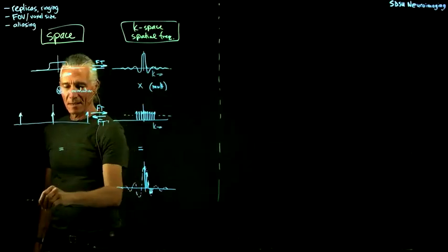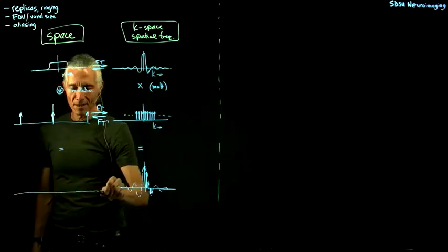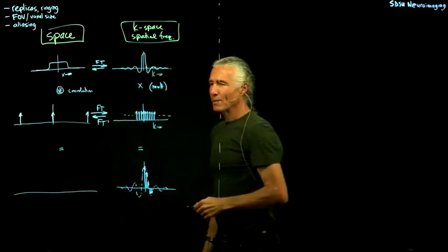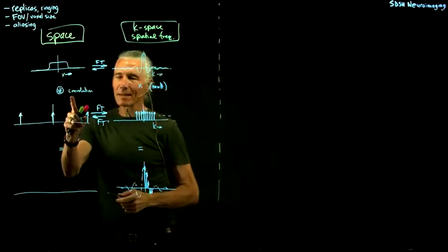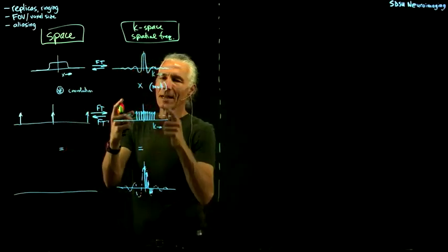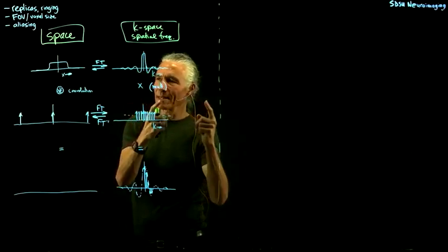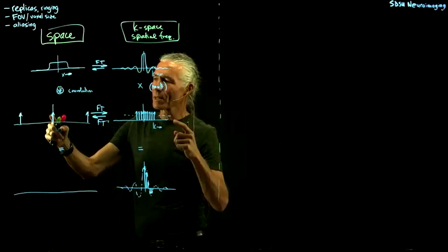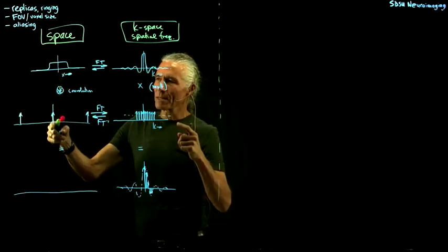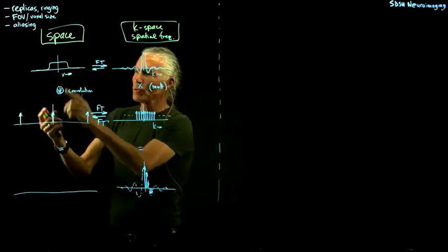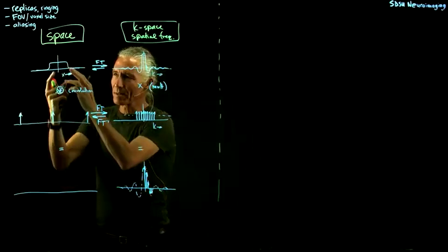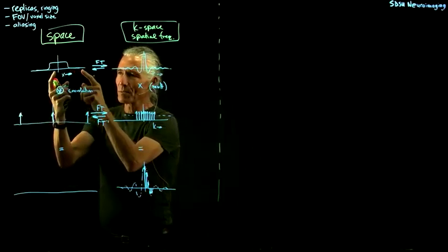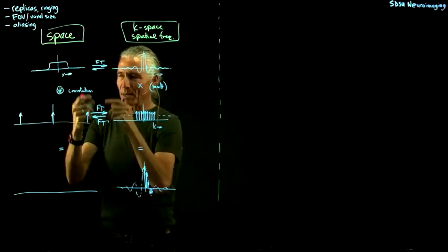And that equals our answer. And so what is a convolution? The convolution is kind of like a correlation done at a whole bunch of offsets. That's the meaning of convolution. So correlate this thing with this function down here, and then move one of the other ones. Like you could move this one, and then correlate again, move this one, correlate again.